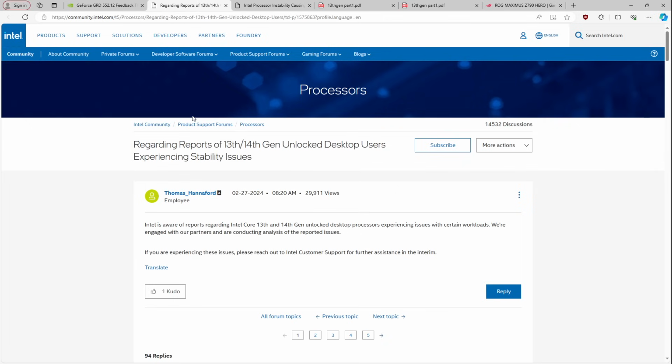So yeah, but if you're concerned about degradation, the easiest, and from my perspective most guaranteed, and I might be wrong about this, I don't work at Intel or AMD or NVIDIA, so I don't really know enough about this, but if you're concerned about the CPU degrading, lower the TJ max, because that reduces absolutely every factor of degradation that there is, as far as I know. Anything related to degrading silicon can be reduced by lowering the temperature.